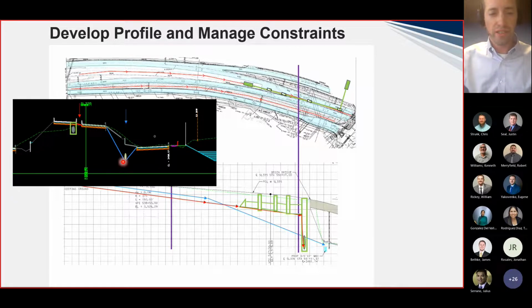And at that point, what we need to do is bring the system underground and implement a retaining wall. And so this has ended up being what we did with this design. So the retaining wall will capture the water coming off the main lanes, and this is sloped somewhere where it will be captured in an inlet. And then this ditch will end,